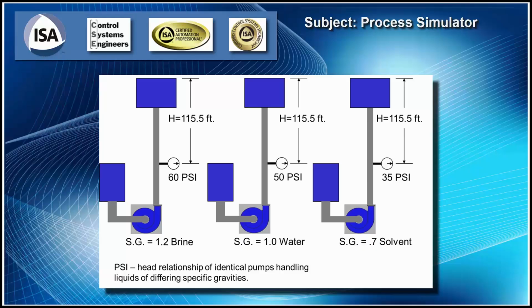And with gases, it's the gas or vapor weight per volume over air weight per volume. And these have to be referenced to standard references so everybody has the same reference. So water and gas will typically be 60 degrees Fahrenheit and 14.7 psia. So make sure that it's 60 or 68 degrees or whatever reference you're using. There's multiple references out there for standards.